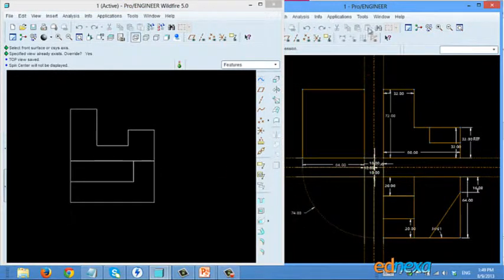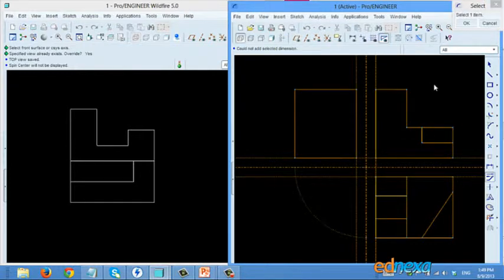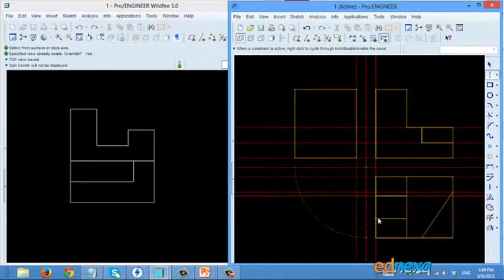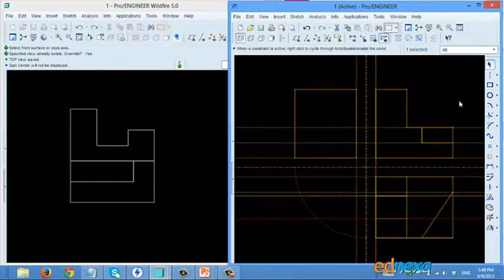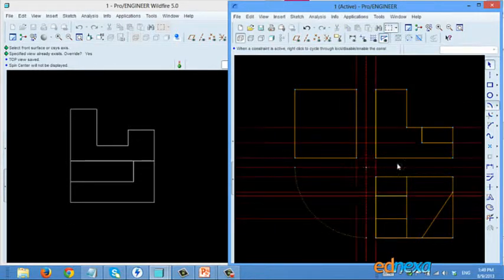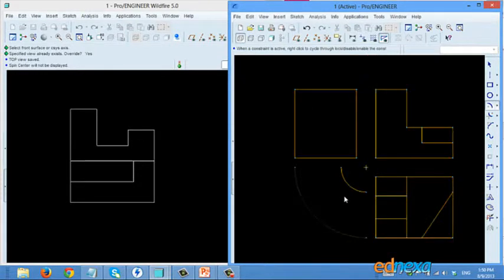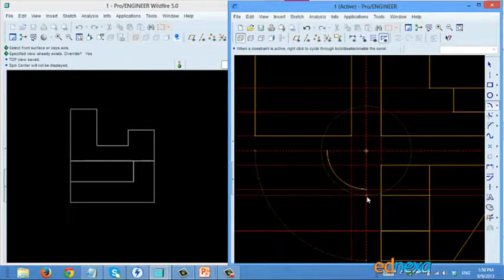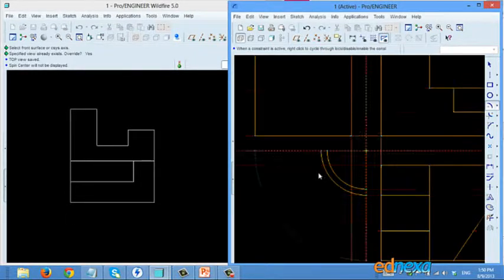So how will I draw this right hand side view? I will take projections from this projection. We have this projection, and then this projection also will have projections from here. So now by the arc method we'll draw some projections from the top view like this.